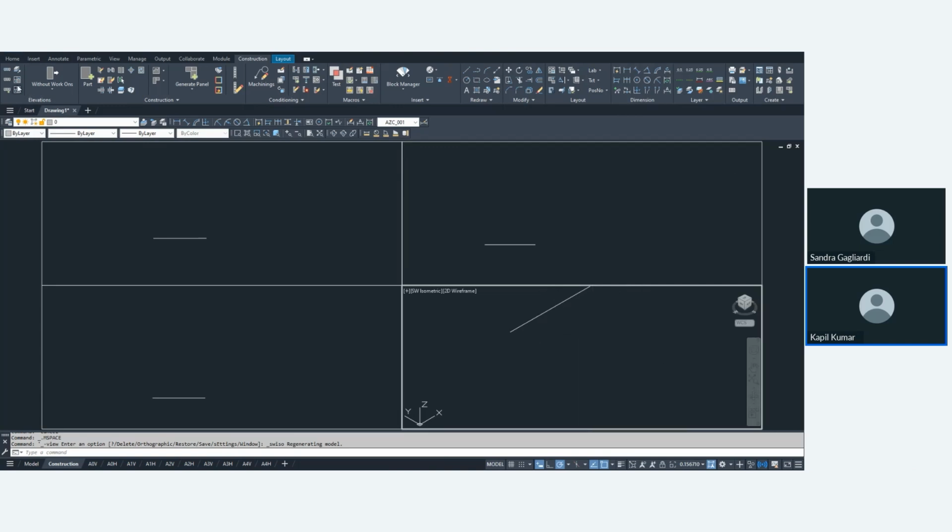In elevation, we have the command isolate object or isolate element. We have hide element here. We have show single element here. Suppose you are hiding a number of elements in your drawing, but you want to unhide a single element which you want to work on, so you can unhide that element from here. Here is unhide all elements. Suppose you have 5 elements in your drawing, meaning 5 parts: top panel, side panel, bottom panel, that you have already hidden but you want to show again in CAD+T. So you can click here, then all the elements or all the parts will show in your drawing.